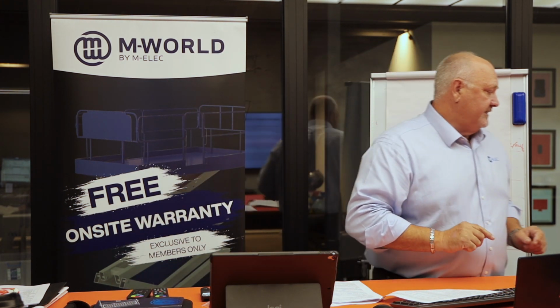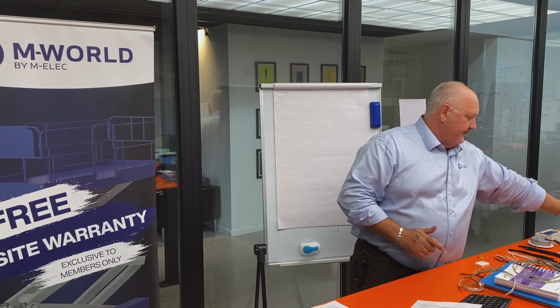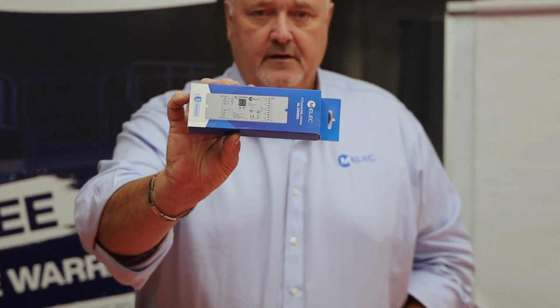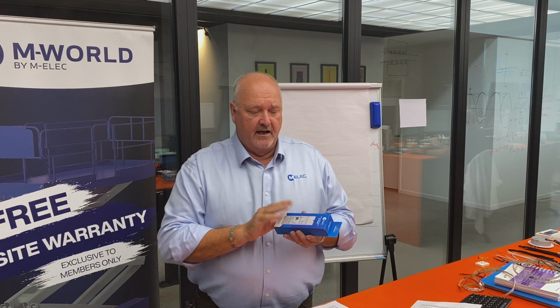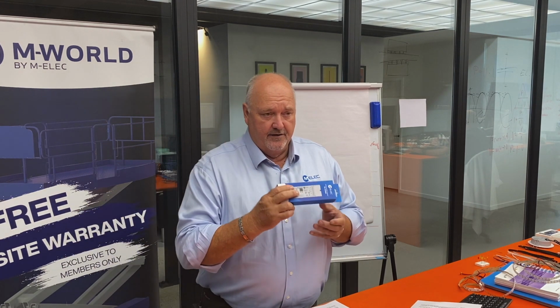The next form is if I've now decided that I want to use DALI. So here is my 4-channel DALI dimmer. This 4-channel DALI dimmer allows me to use the DALI bus and give it an address. There is a series of dip switches on here which allow me to program it, so it's a programmable controller.